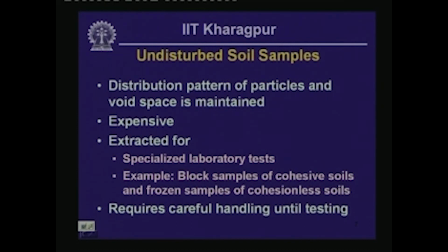Now, these undisturbed soil samples are used for specialized laboratory tests, and these are tests that are particularly affected by sample disturbance. Examples of undisturbed soil samples include block samples for cohesive soils and frozen samples of cohesionless soils.